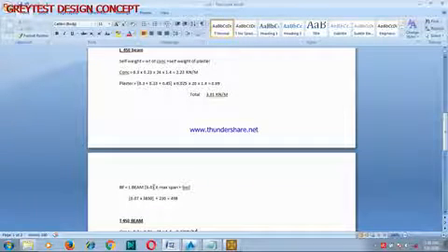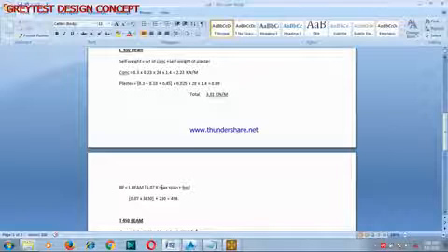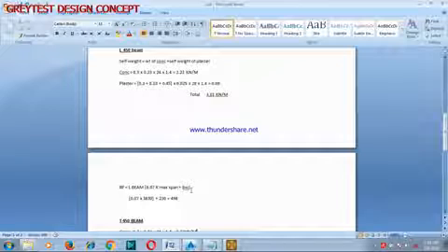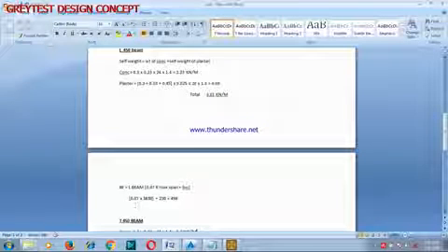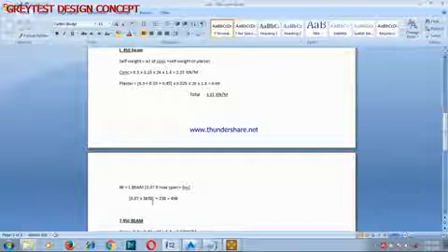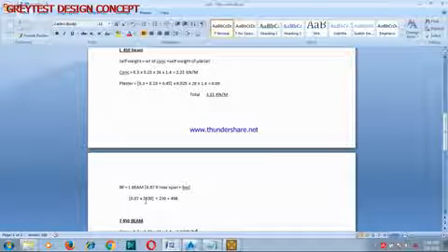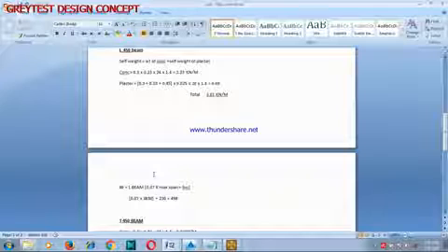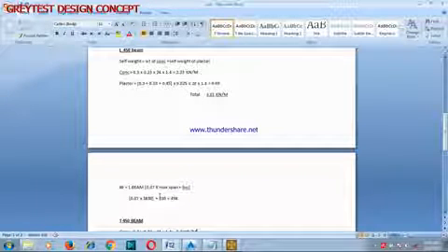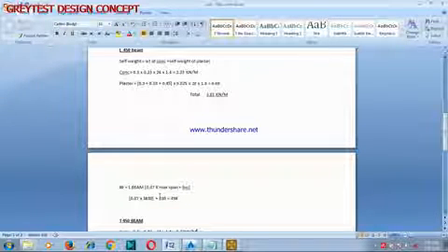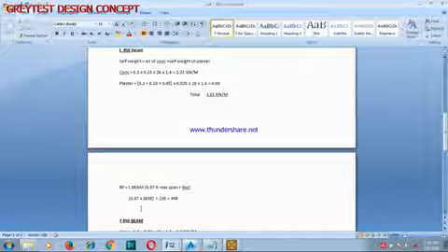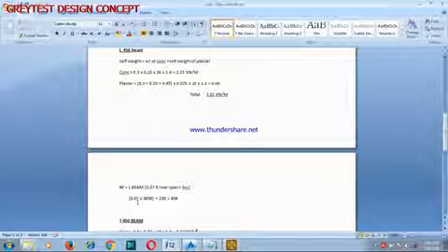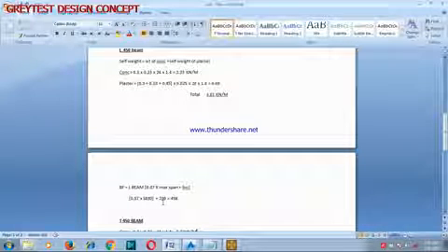Okay, 0.07 times the maximum span, then plus your breadth of web. Now on that beam 1, you will notice that the maximum span is 3830, although all the spans are actually equal. So on a beam that has different spans, you pick the highest value, multiply by 0.07, then add your 230.